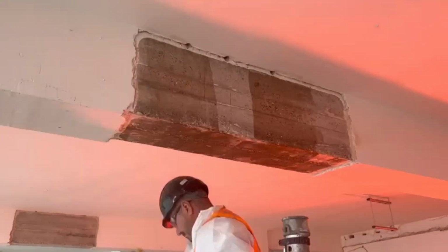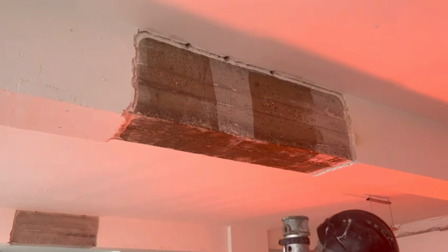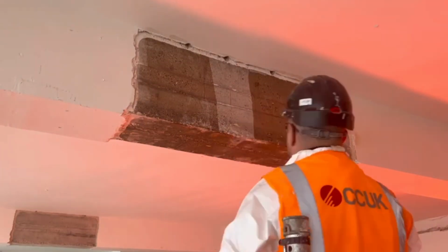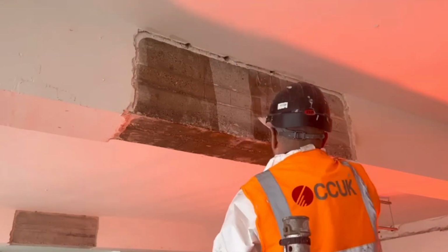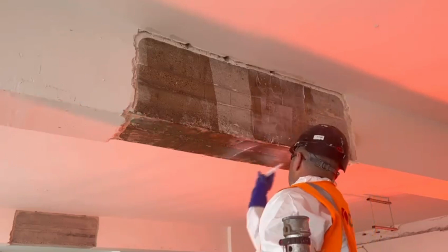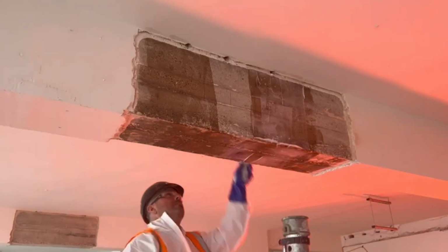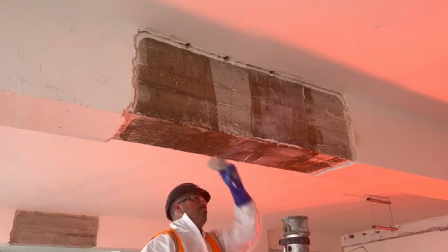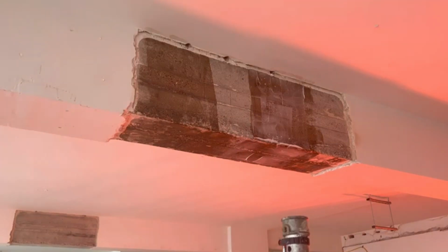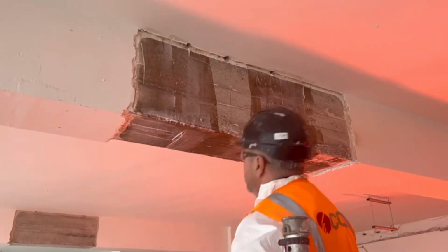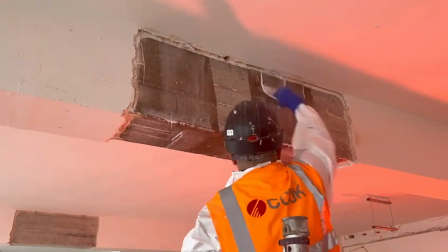But the other thing which is quite important to note here is that the carbon fiber they are applying is saturated in a different area on the same site. So when they're applying it, it's in wet condition. So that's why this application is called wet layup method, and all the fabric application needs to be wet layup method. You should avoid doing dry layup, and it is more or less abandoned now in Europe.